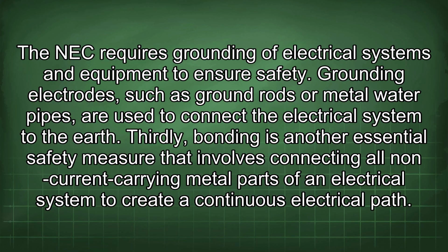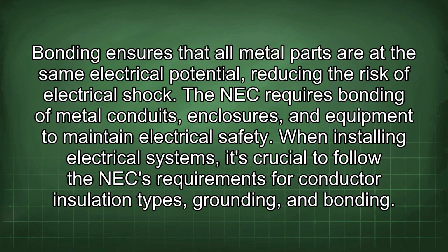Thirdly, bonding is another essential safety measure that involves connecting all non-current carrying metal parts of an electrical system to create a continuous electrical path. Bonding ensures that all metal parts are at the same electrical potential, reducing the risk of electrical shock. The NEC requires bonding of metal conduits, enclosures, and equipment to maintain electrical safety.